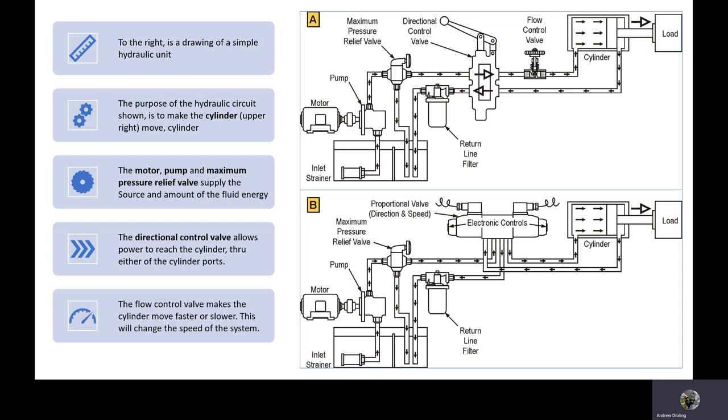These valves are a little bit more common now, as you can use a remote control 24 volt DC or 120 volt AC switch to remotely control the actuators, which can be located meters away from the actual cylinder.